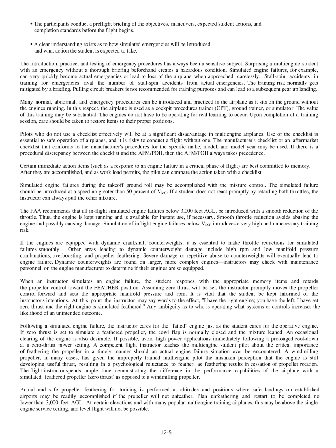The FAA recommends that all in-flight simulated engine failures below 3,000 feet AGL be introduced with a smooth reduction of the throttle. Thus, the engine is kept running and is available for instant use, if necessary. Smooth throttle reduction avoids abusing the engine and possibly causing damage. Simulation of in-flight engine failures below VSSE introduces a very high and unnecessary training risk.